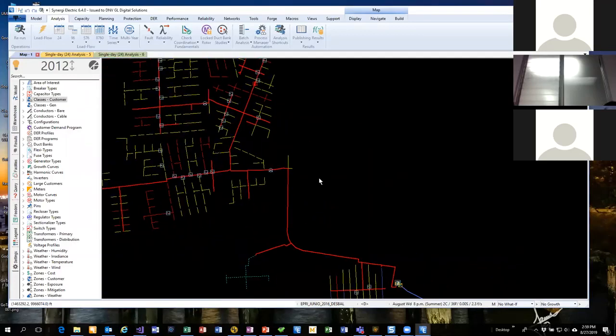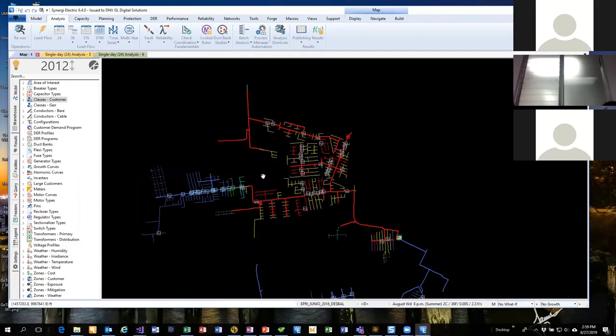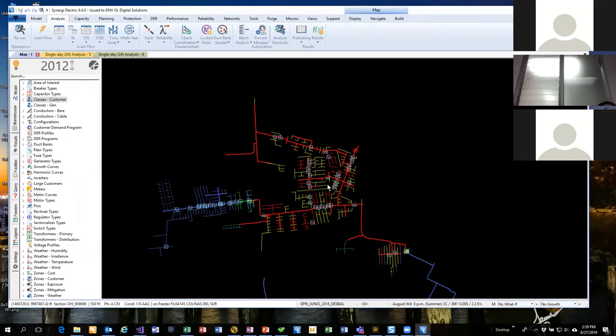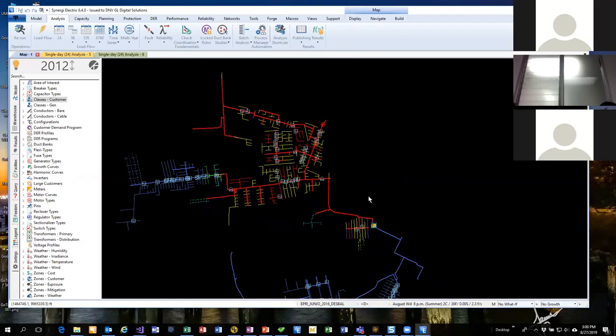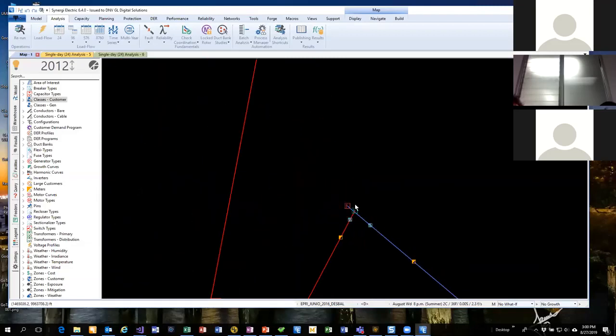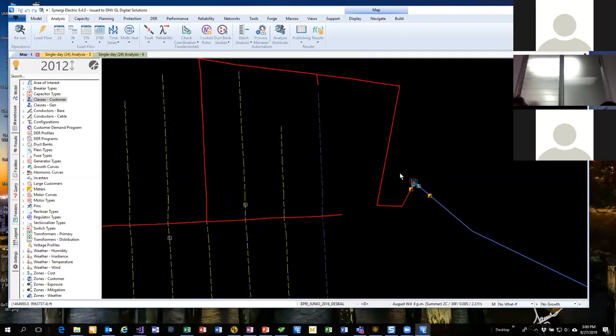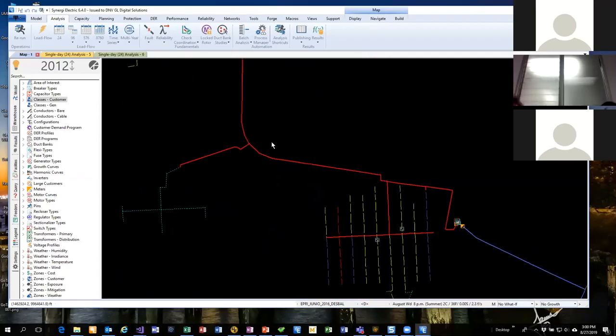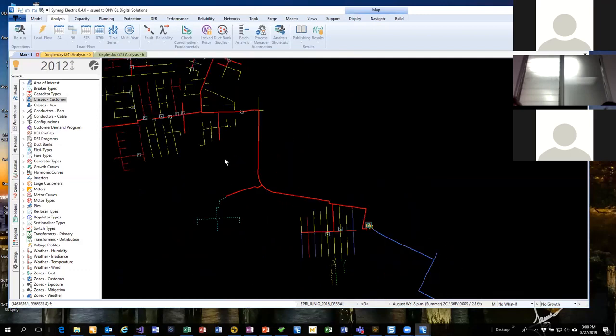So now we're able to model the PD, or I'm sorry, the loads, and that's very important. There are three things that are very important to doing DER studies, connection studies, those sorts of things. One is some sort of time-varying load model. The second one is the solar generation model. And then the third one is a substation. And I noticed you don't have substations on these feeders. We could talk about that later, but there are different ways to get a substation built into these.